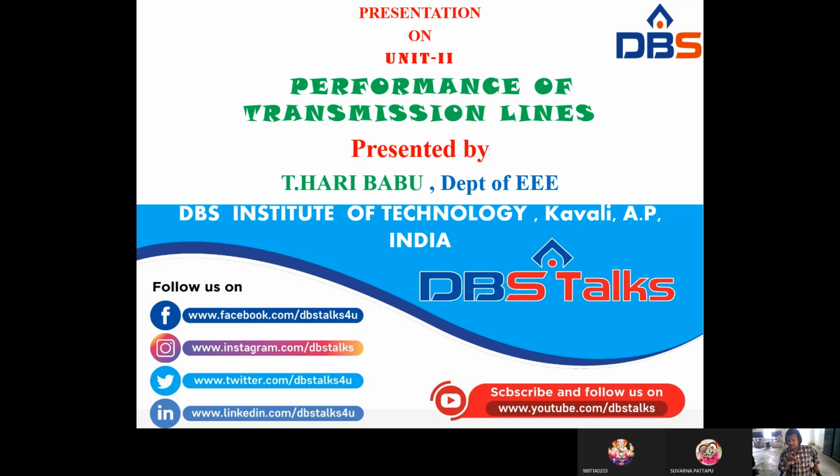From that, we get sending end current and sending end power factor. Efficiency is VR IR cos φr divided by VR IR cos φr plus losses, 3 I square R copper loss, right? Like that we have to discuss it and solve the problems also.